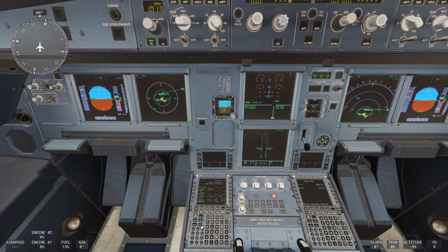So as we can see here, we're coming out of Gatwick, runway 26 left. Immediately after takeoff, we're making a 180-degree turn round to the right hand side, following ourselves over to Acorn, and then at D258K, we're then making a 90-degree left hand turn to follow and complete our departure sequence up to the Lambourne waypoint. We're then following the route all the way up to the northwest.